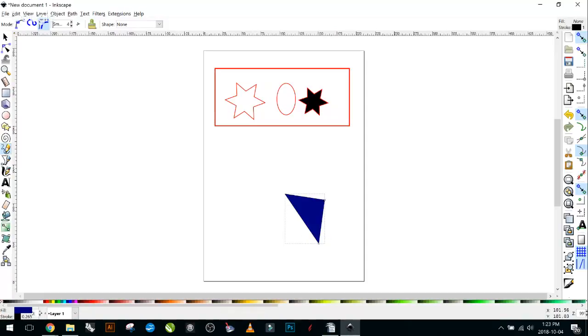You'll see once your shape is closed, it can now be filled. So if for whatever reason you're trying to fill your shape that you've created and it's not filling, most likely you have a node that's very close to being closed that you can't see with your eye, but it's just not fully closed. So make sure that you're doing this. This may be annoying. It is annoying for me, I can say from my experience. By annoying, I mean you have to click on a node again to continue that shape.